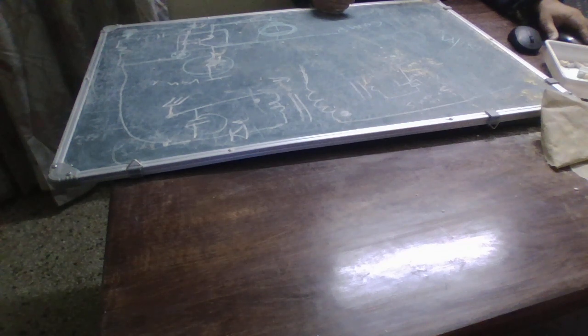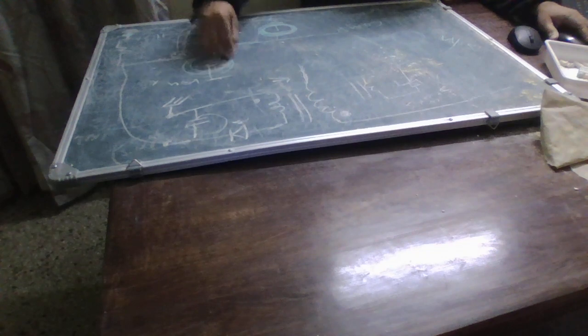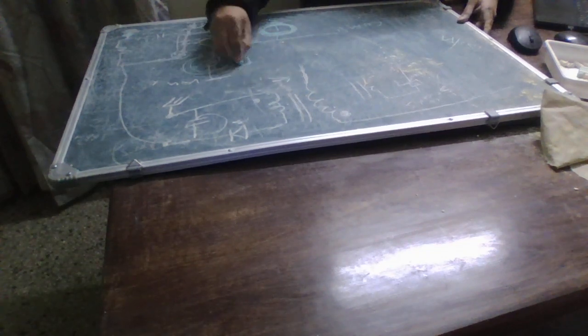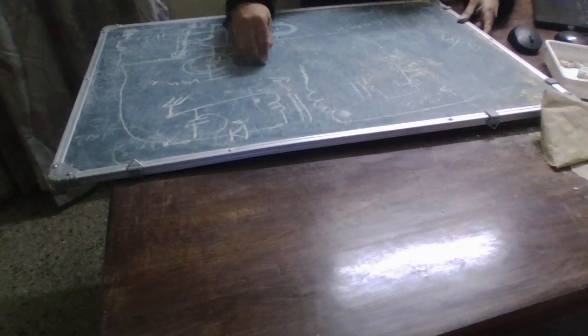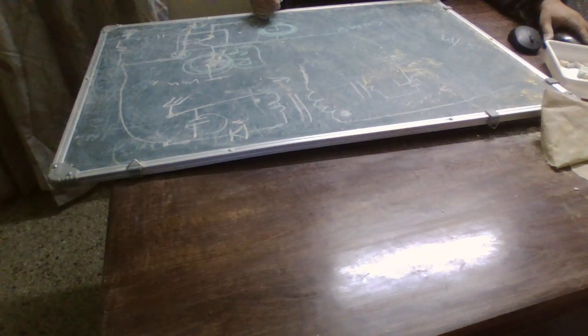We should take the compensating capacitor greater than this parasitic capacitance. So a pole is going to form by this resistance along with the parasitic resistance. It is going to form one pole here, and now we need to place the zero and poles on the feedback path to achieve stable operation.